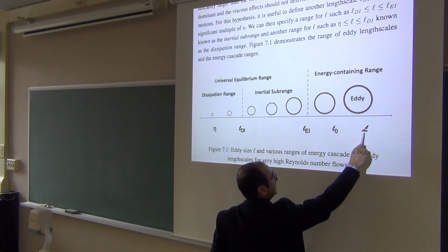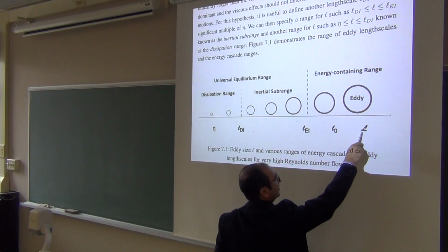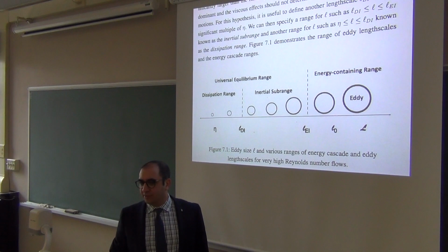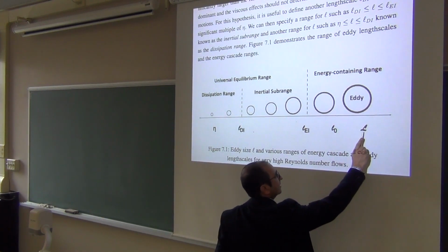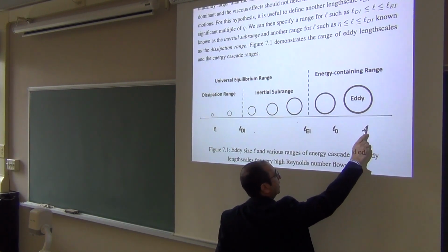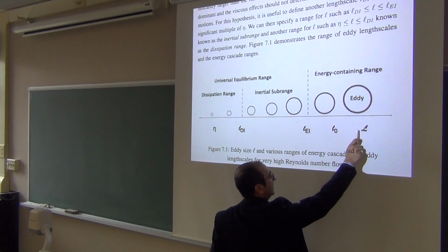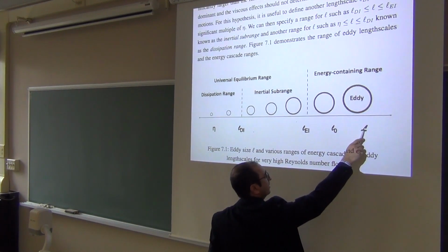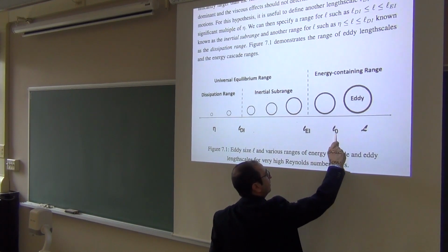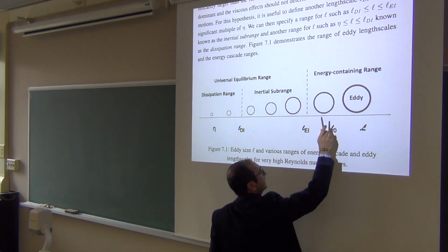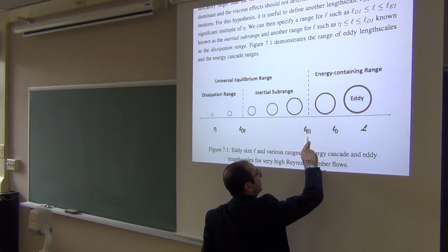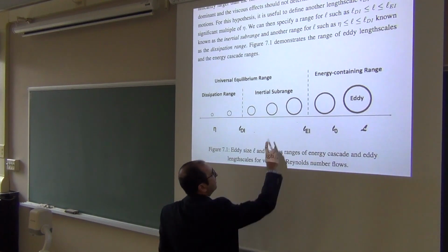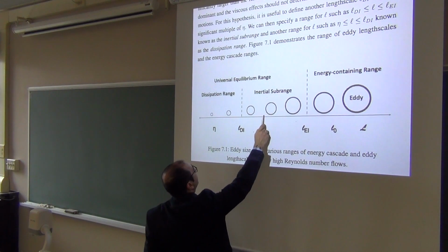This big L is the length scale of the problem. This could be the size of a building or the diameter of a pipe around which turbulent flow is occurring. So that's fancy capital L. Then the largest eddies that form in the system are very close to the length scale of the problem. We know them by L sub naught. So it's that eddy. Then this is the cutoff eddy length scale, L_EI. And then after this, the equilibrium universal range begins.